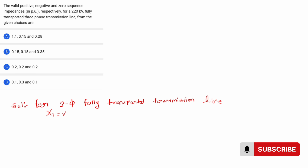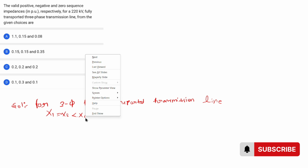The condition is X1 approximately equal to X2, less than X0. See in the options which option is based on this: X1 equal to X2 is less than X0. In the given options, positive and negative and then zero sequence impedance are given.